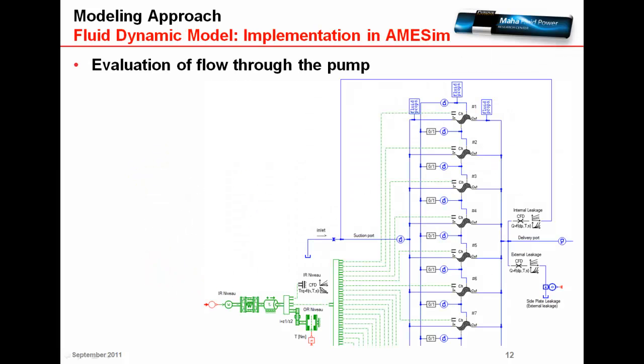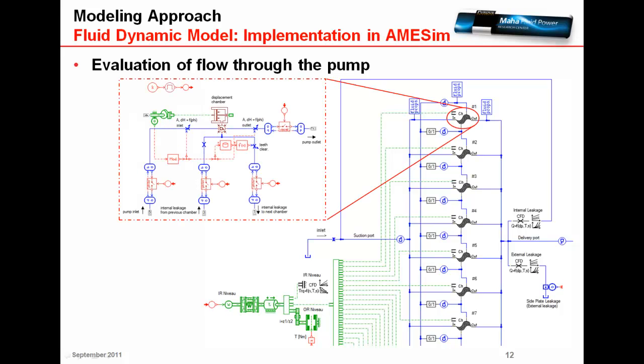This is how the fluid dynamic model looks in the Amesim environment. It is based on the lumped parameter approach and contains a finite number of displacement chambers. This is a look inside the chamber element, and these icons represent the equations I have already explained.